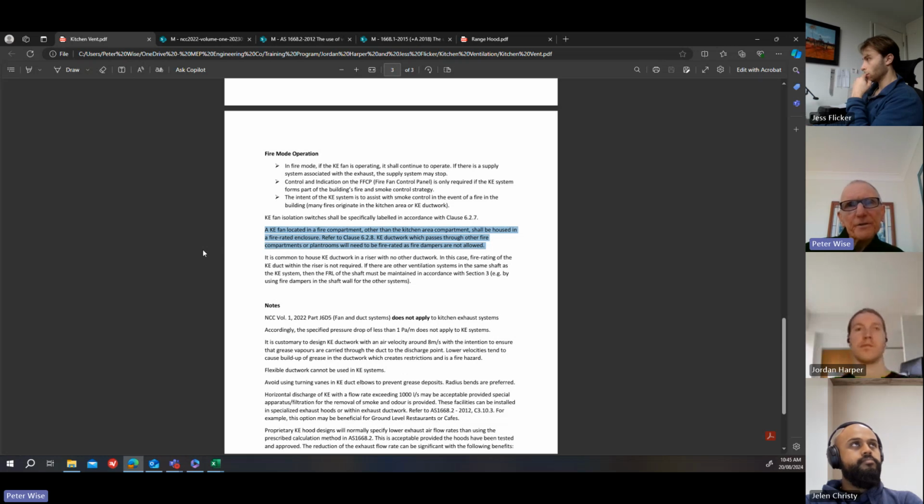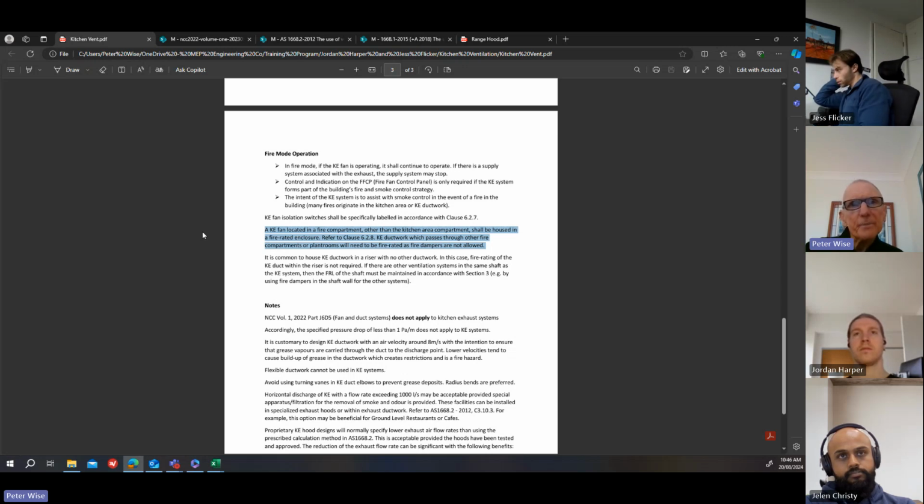I'm a bit vague on this because it varies from job to job. One I worked on was a hospital in Sydney, which had a large commercial kitchen. Adjacent to the kitchen, there was a plant room which had the kitchen exhaust fan plus other air conditioning equipment. In the initial design, there was a firewall between the kitchen and the plant room. So everything in the plant room on the kitchen exhaust side had to be fire rated.